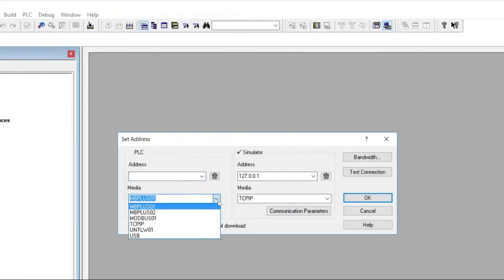The next one that we also spoke about was USB. If you're using USB, most likely you don't have to specify anything under addressing, but stand to be corrected depending on the software that you are using. If your engineering workstation can pick up the PLC in Device Manager, then you are good to go and you can connect with the PLC.